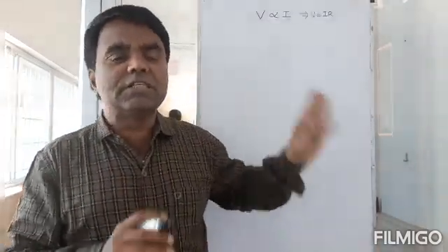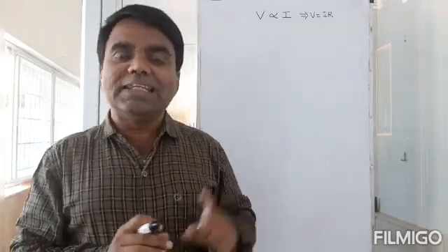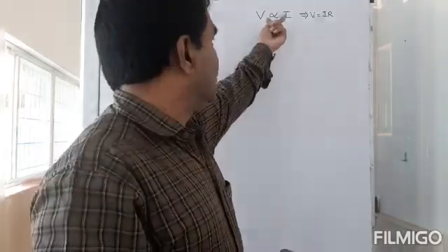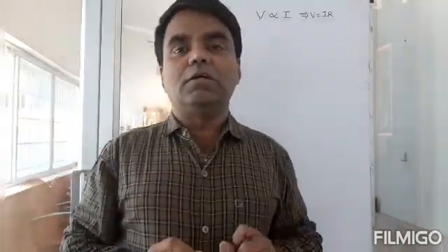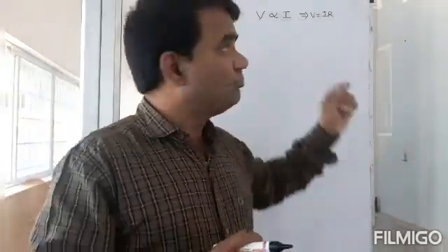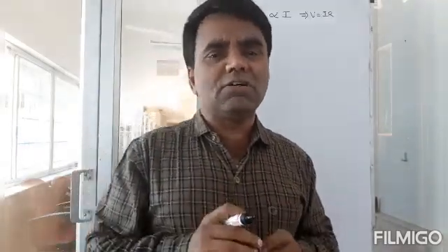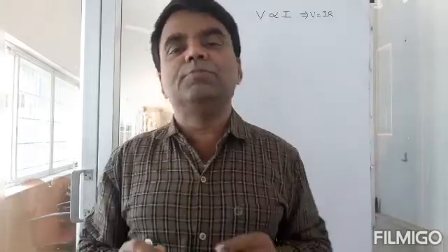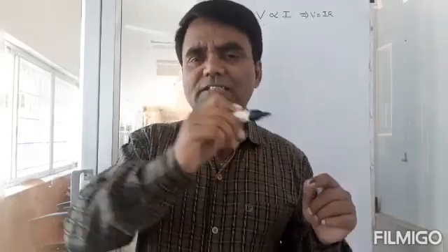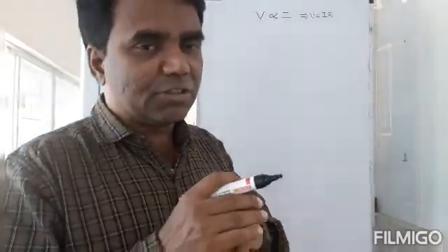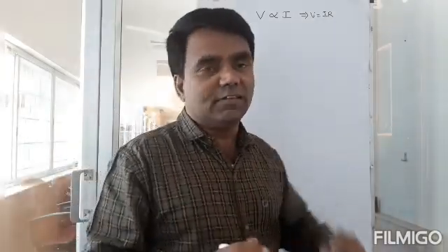So this equation tells you that you have a linear relationship between voltage and current. It's a straight line. That's what you get from here, because V is equal to IR, where R is going to remain the slope of it. But that is not the case, basically. It works okay over a range of voltages, but as you keep increasing the voltage, you don't really get a linear relationship. The relationship is slightly off linear.